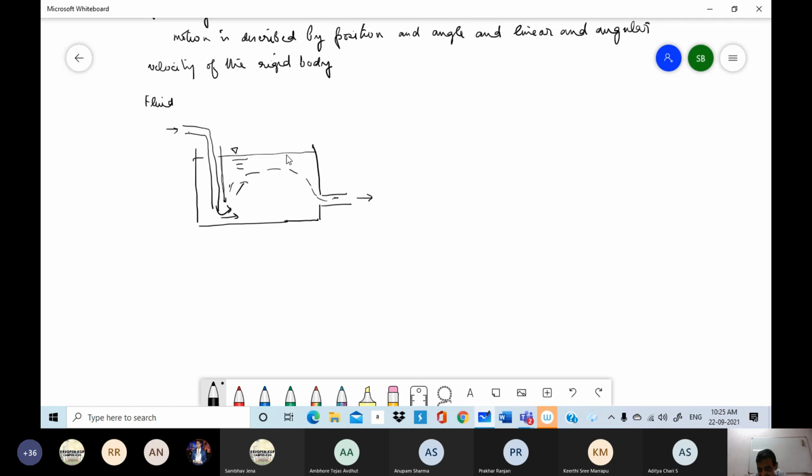At a microscopic level it consists of molecules which move around at random. But then we assume in fluid mechanics that all variations, say the length scale over which velocity changes significantly, are over a length scale significantly larger than molecular scales. So on that length scale, it can be considered to be a continuous material.